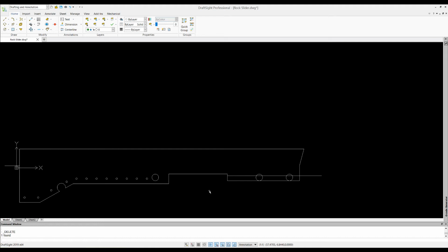There we go. There's the bolts for that side. And then keep in mind we will end up adding a gusset in this open area to stiffen it up a little bit out here in this corner so that it's not sitting on its own. But I don't know exactly how we're going to do that yet, so we'll just leave that alone. We'll probably weld it onto here and then put another bolt pad on the side of the frame. And we'll just come up with that as we need it.